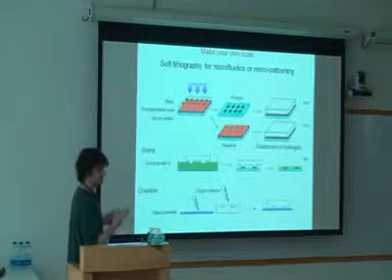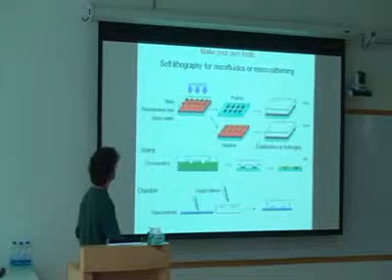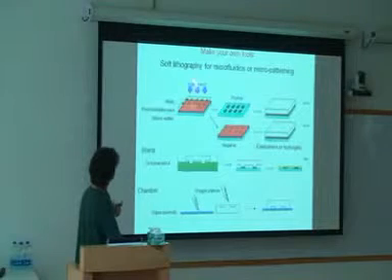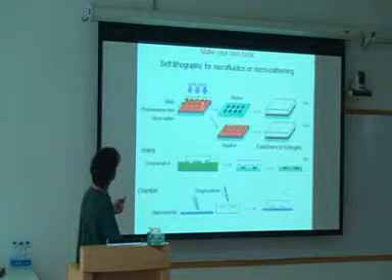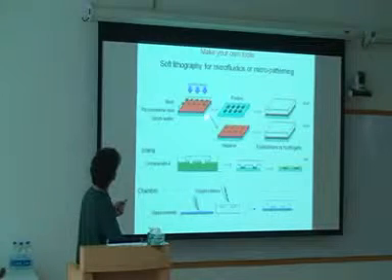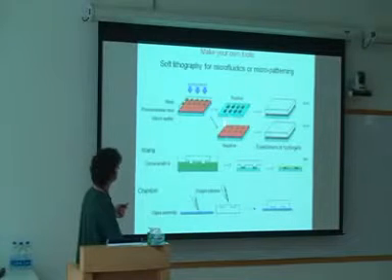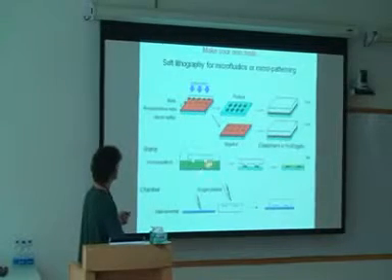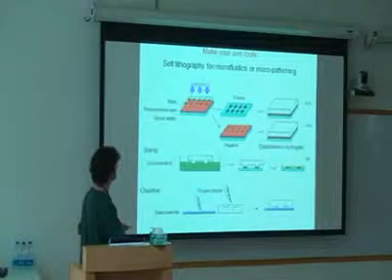This is summarizing the fabrication technique, which all the different things rely on. You have a material which is sensitive to UV, and you have a mask, and you shine UV through your mask, and the regions which are illuminated with UV change properties, so either they get destabilized or they get stabilized, and then you make a sort of mold. This mold can be used to mold whatever you want, elastomers, hydrogels, and with that you can make stamps. Those who follow my session have seen these stamps, and you can stamp protein.